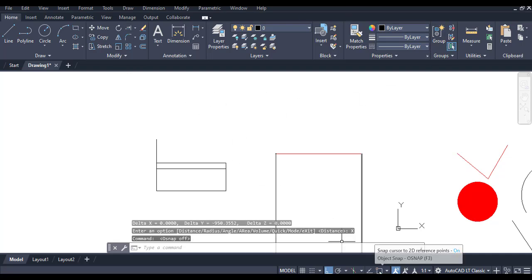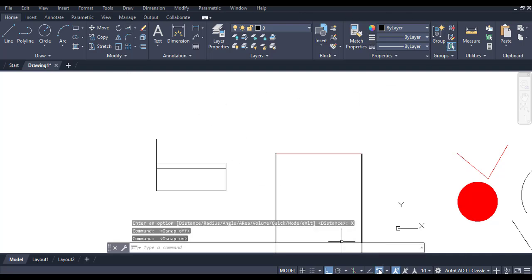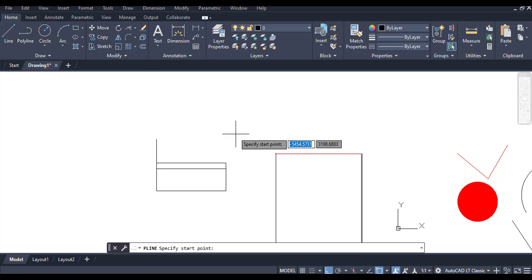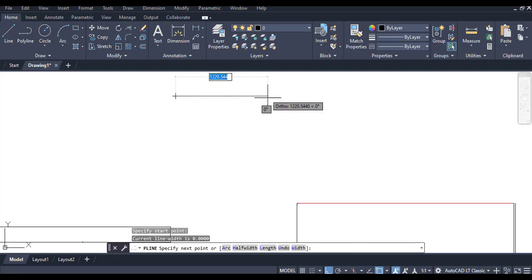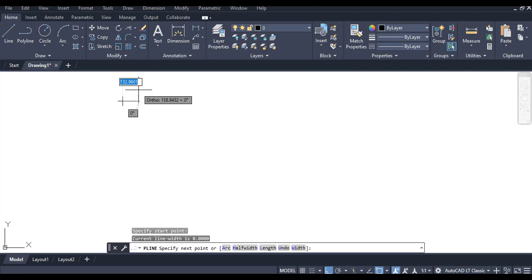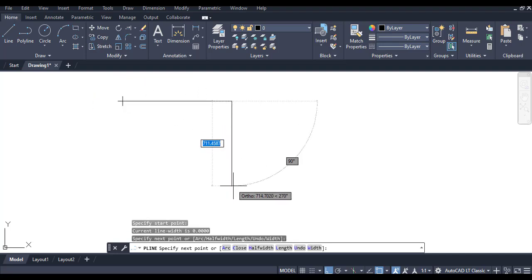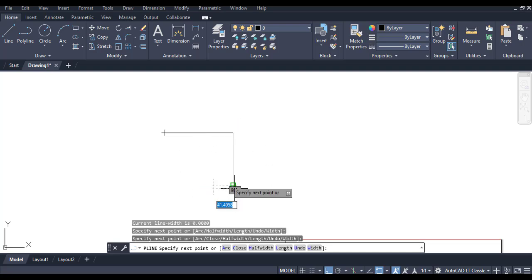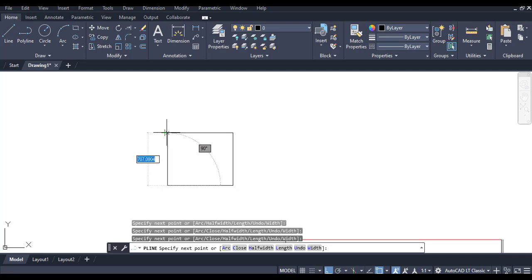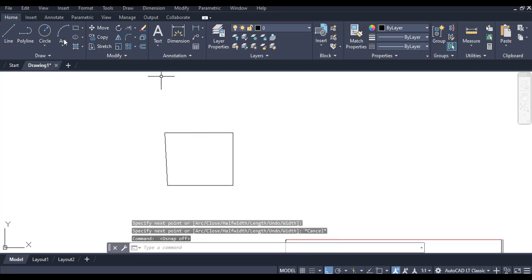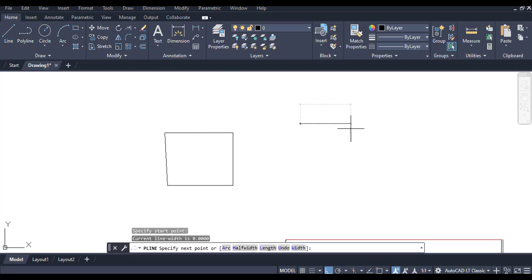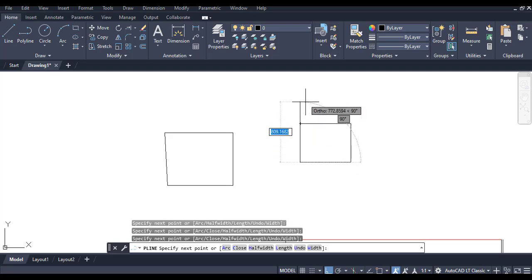Right here, this OSnap, if I click on OSnap here, you see when I'm working here, there's a point that shows me a box. That's the function of the OSnap. It literally tells you where to join an item with another. But when I click it off and I'm working, you won't see that box displaying anywhere. You see, that's the difference. It's not displaying. That's the function of the OSnap.